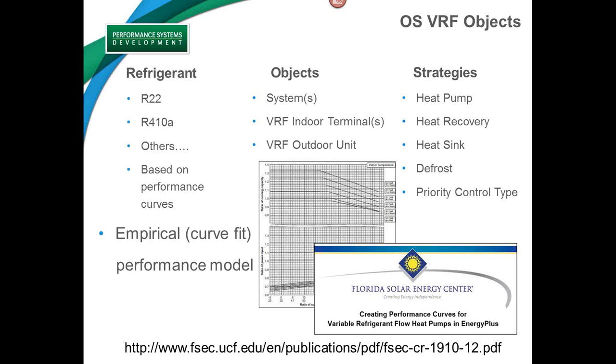So you'll see in the center of this slide an example of a performance curve for an indoor unit. Some manufacturers provide this data in a tabular form, some in a graphical form. At the bottom right is a key document. If we're going to model VRF systems in EnergyPlus, the FSEC, Florida Solar Energy Center, published a great document walking through, step by step, how to create those performance curves for VRF heat pumps in EnergyPlus, or now in OpenStudio.